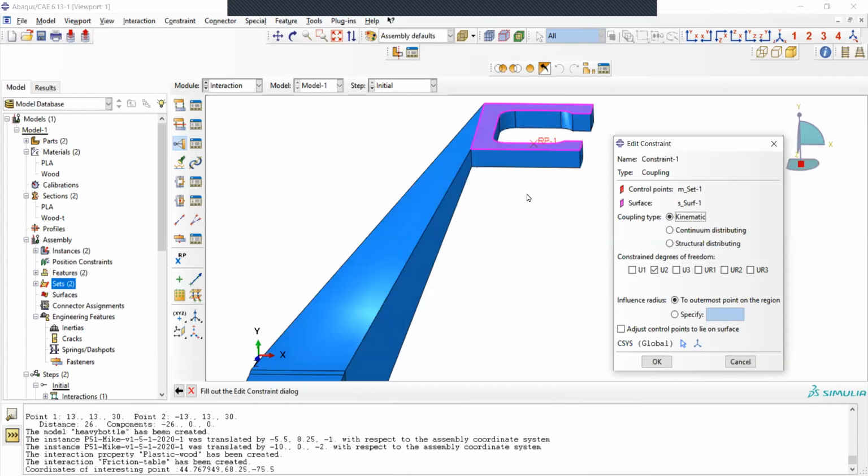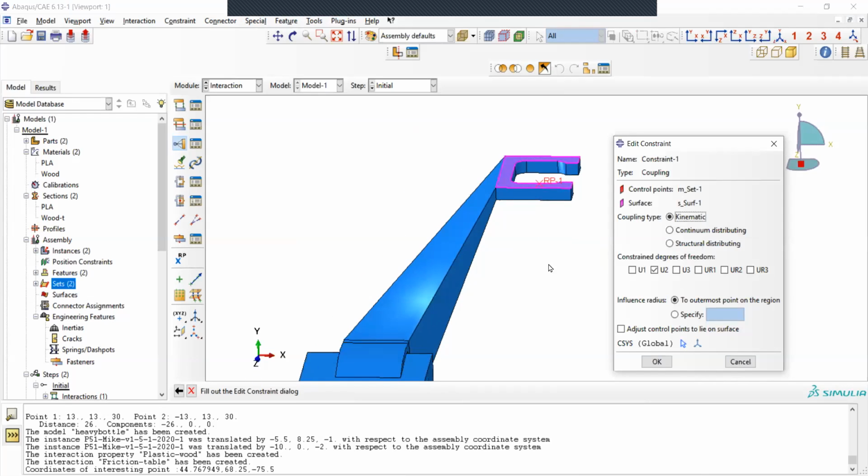That means all the forces will be only affecting the surface downward. And if the surface wants to travel forward, it wants to rotate, it can rotate freely. I hope you understand what I'm trying to explain. So I'm trying to decouple the vector of force from the surface so that the surface only has a force downward, but the surface can move in all directions, because it will need to bend and rotate and twist. So I give it that freedom by only coupling in the force downward.